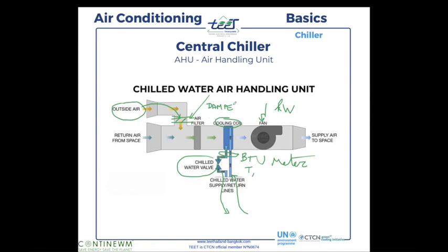And some dampers are regulated because basically the idea is to bring oxygen. If you are in a big building with a lot of offices, then the dampers are in general regulated automatically. They measure the quantity of CO2 inside of the office. So sometimes we have sensors that measure how much CO2 you have in the building, and if they have too much CO2, then they open the damper automatically and bring some more fresh air. So we cannot block the damper.